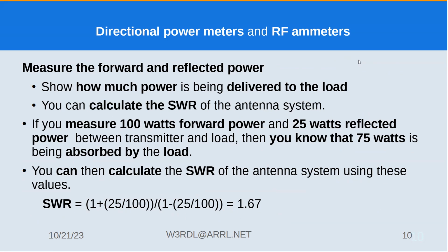Is that why sometimes you get a good voltmeter, and before you use it, it's at 0 volts, but sometimes the last few digits will start talking nonsense? Yeah, because you've got test leads, and you're picking up noise. So a good voltmeter is not inaccurate, but it's picking up garbage. Well, depending on how long your test leads are, it doesn't matter how good the voltmeter is. They're going to act like an antenna if there's RF around.